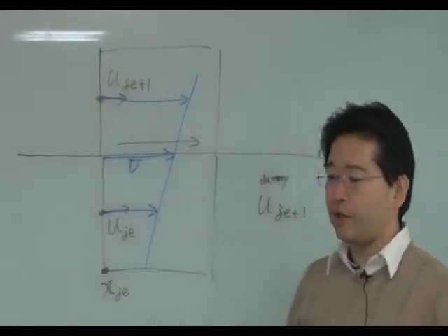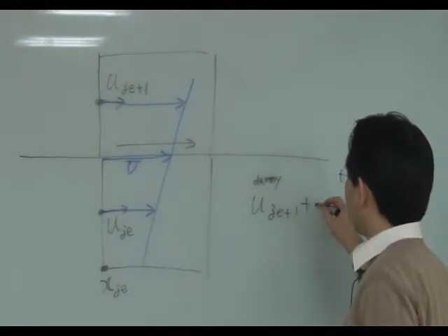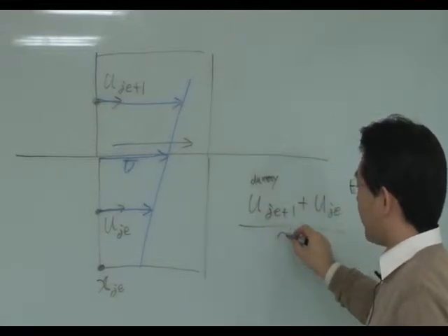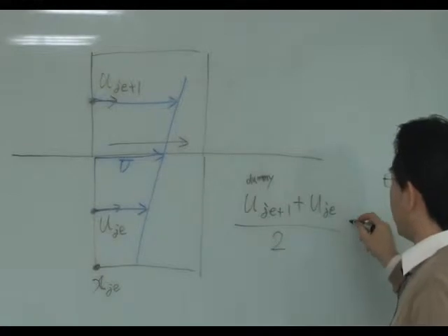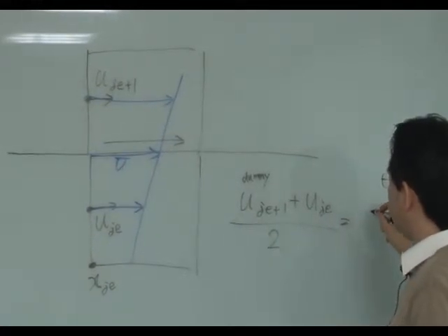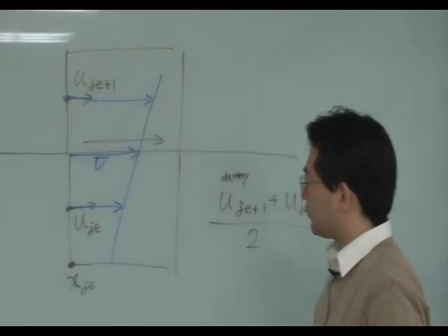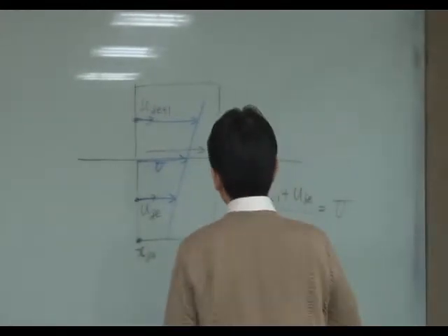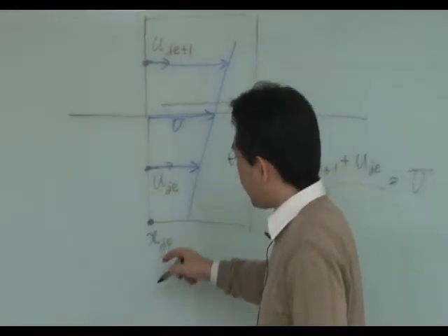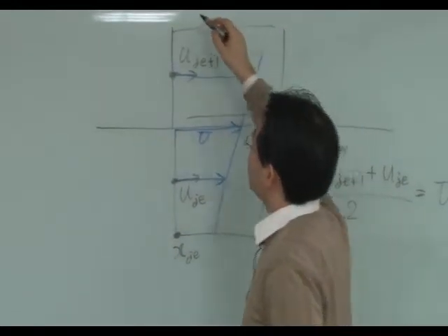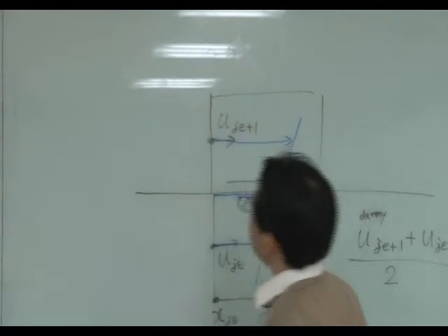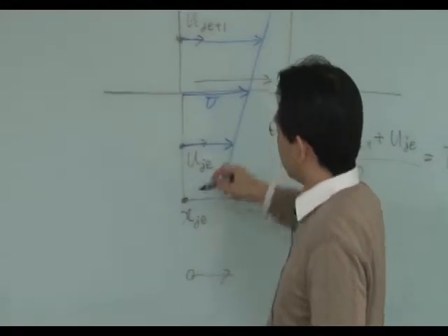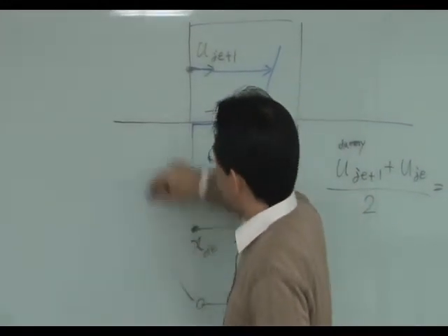It is not calculated in the simulation. And this one is the first velocity point inside the fluid boundary. Its mean value should be the given velocity of the moving wall. Actually, you have two or more boundary dummy points. So you have to copy this value to this one.